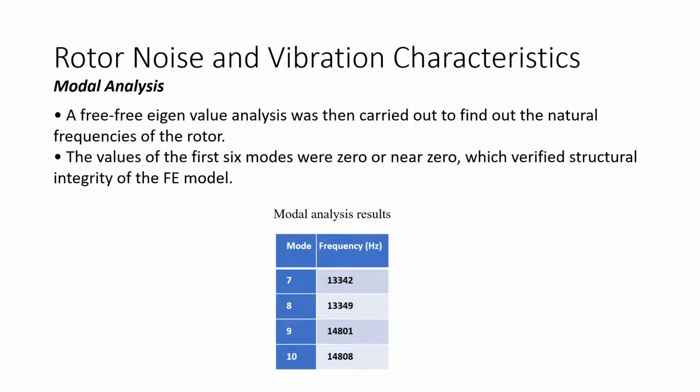So if the rotor is considered as a cylinder, it has a diameter of around 5.5 centimeters and a length of 8 centimeters, and hence its mass is very low. And we know that natural frequency is inversely proportional to the square root of mass, and hence because of low mass, the natural frequencies of the rotor are so high. And if anyone wishes, you could email us, and we could send our hand calculations for calculating the natural frequencies.